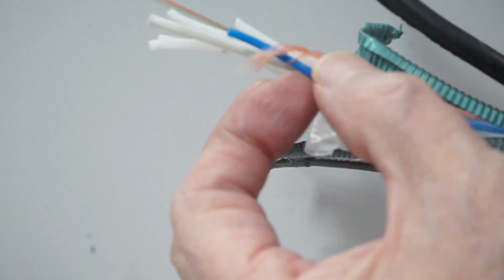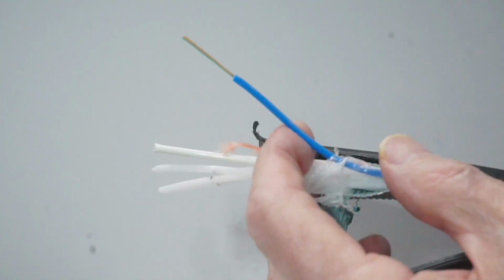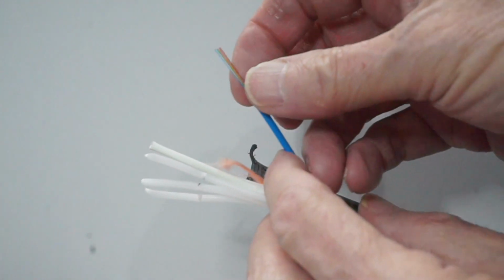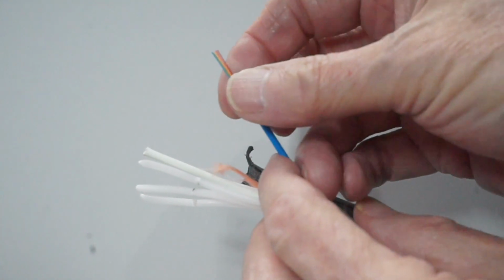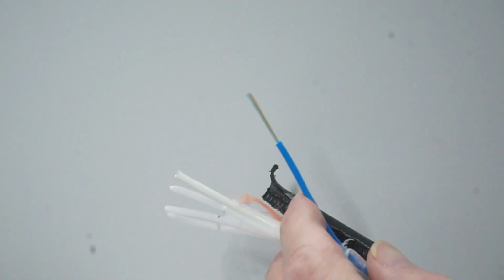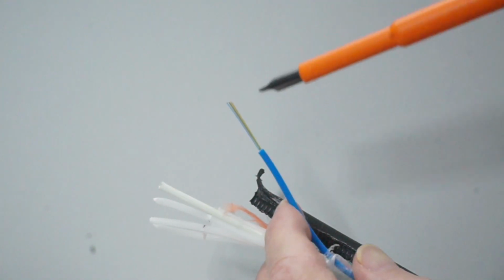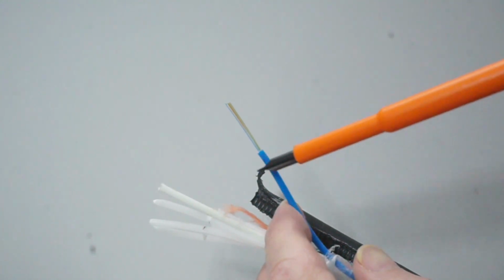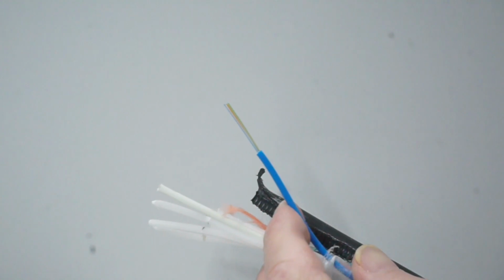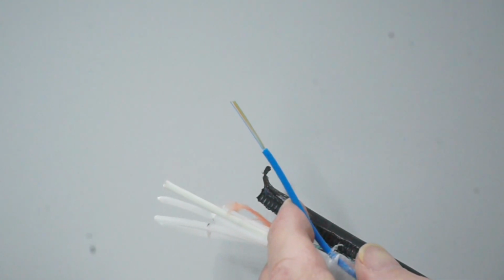So where are the fibers? Well, they're actually inside of this blue tube. That blue tube is called loose blue tube construction. And this has 12 fibers on the inside of it. The 12 fibers are passed through the tube, and this one is non-gel filled. The manufacturer needs to keep water from ever getting inside of that, and so they can put a gel in there. This is non-gel filled, so it has some type of material that expands if water should get into it.